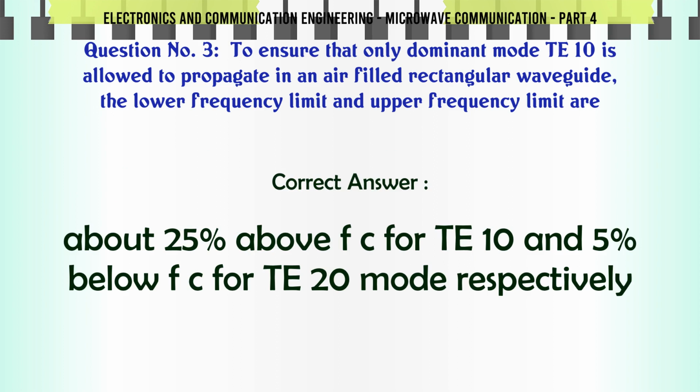The correct answer is about 25% above Fc for TE10 and 5% below Fc for TE20 mode respectively.